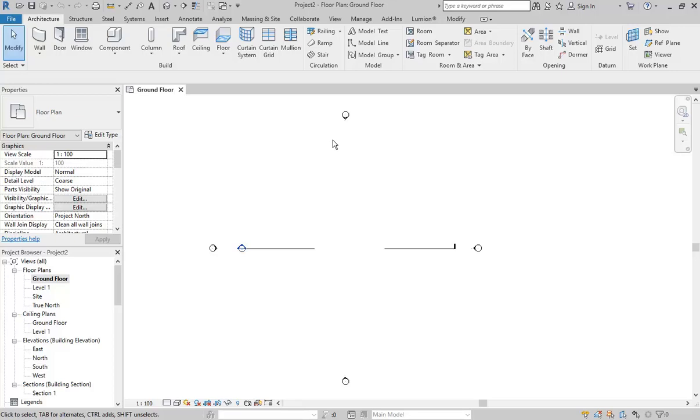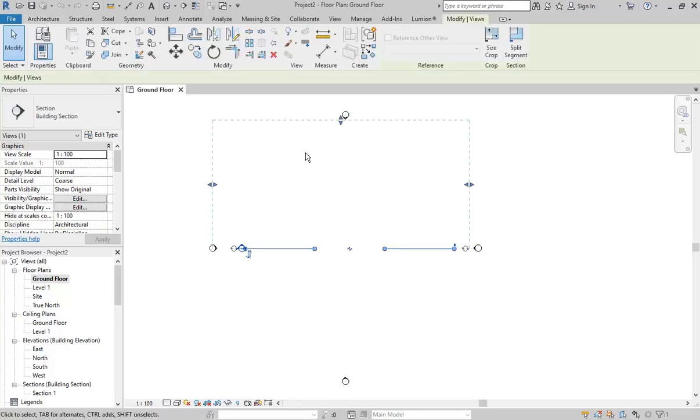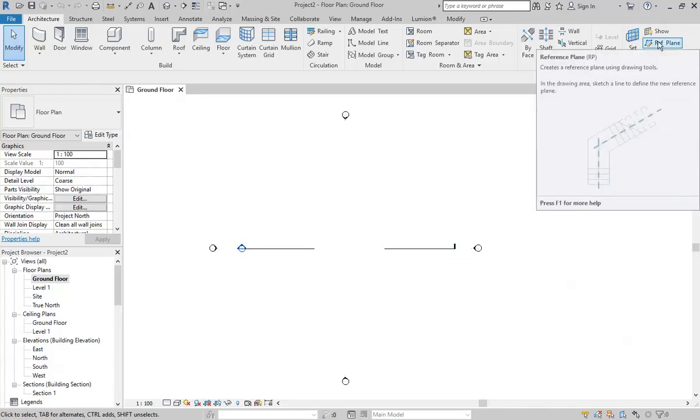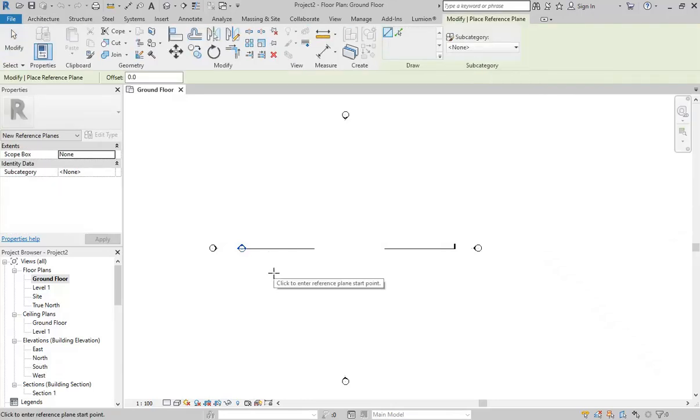And so I've got the 4 elevation views that you've just seen, and then also the section line to tell me basically where the centre of this view is. So we're always looking for that when we first start drawing. We want to draw in the middle of those 4 views and also that section line. And so I'm going to draw some reference planes now, starting with one that crosses over that section line, it's the vertical plane.